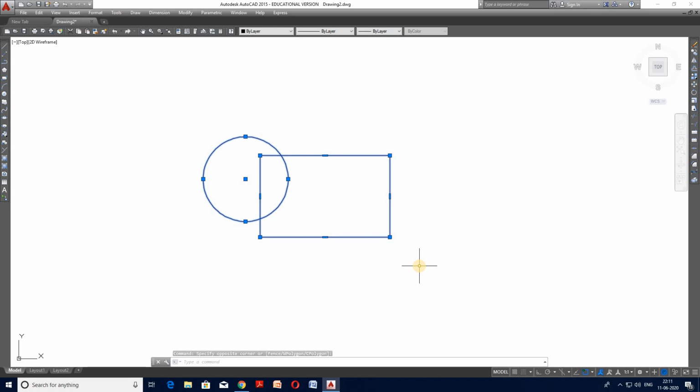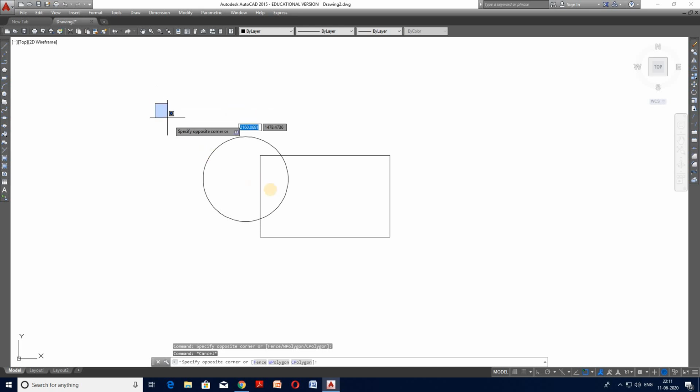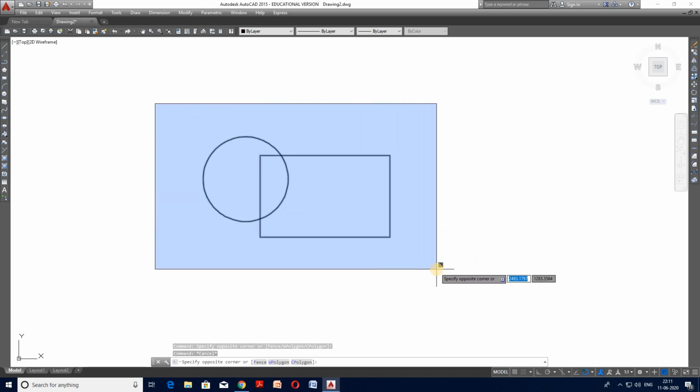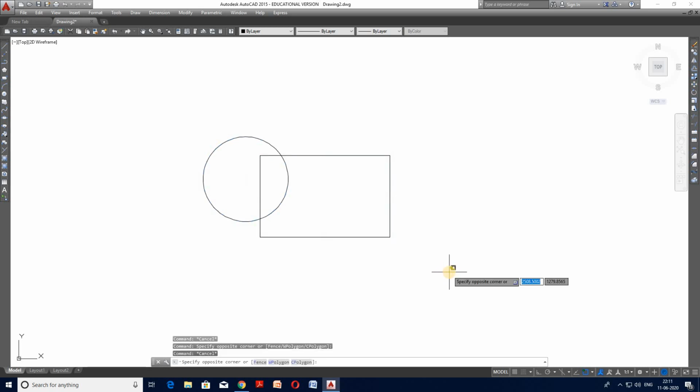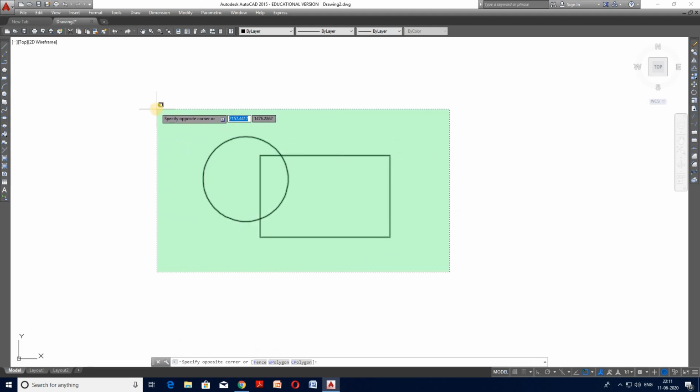This is one option by using left to right movement. So left click, move towards right, include all the content in that blue rectangle, and then press left once again. The second option is click on the right outside the drawing, move your mouse towards left, then a green rectangle with dotted boundary will come, and then click.